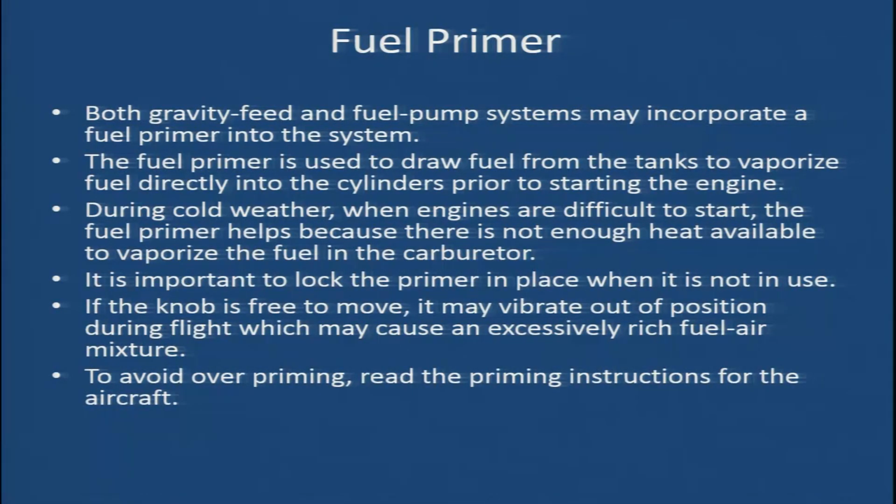During cold weather, when engines are difficult to start, the fuel primer helps because there is not enough heat available to vaporize the fuel in the carburetor. So, during cold weather operations also, when it is difficult to start the engine, this fuel primer is used for starting the engine. It is important to lock the primer in place when not in use.